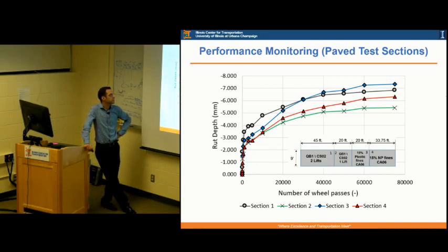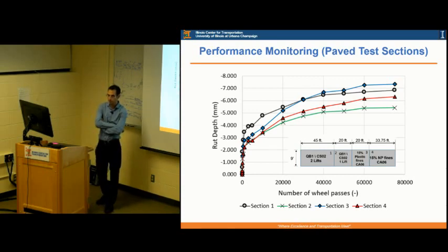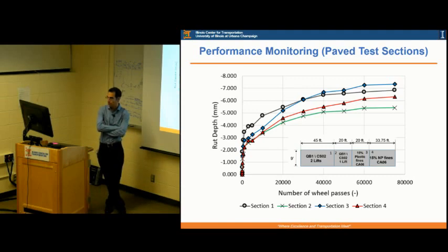Whereas if you look at section 3, which is the worst, with plastic fines, after about 3 millimeters it just goes very high. The slope is very high, and even the slope of the 15% non-plastic fines is high compared to the QB section. So QB is really performing in a low to medium volume road with 4 inches of HMA better than even the CA6 of 21 and 24 inches in this case.